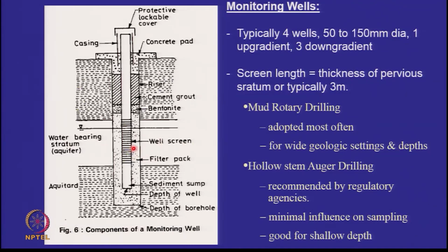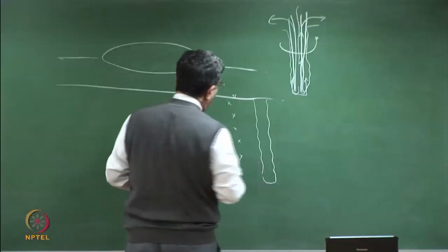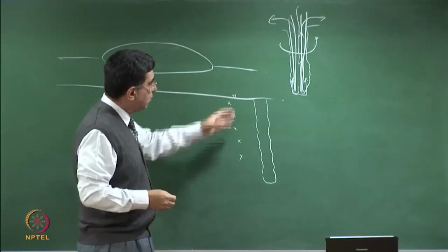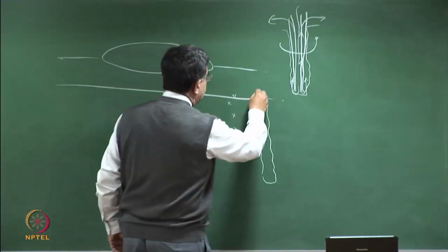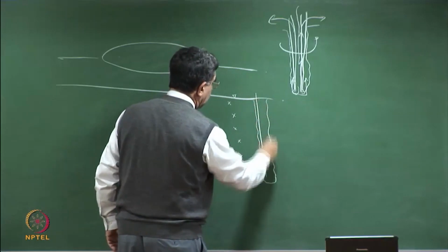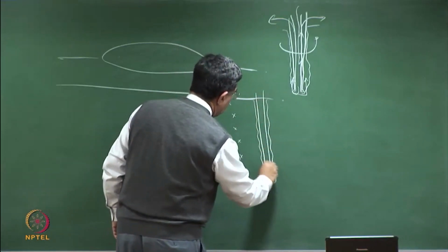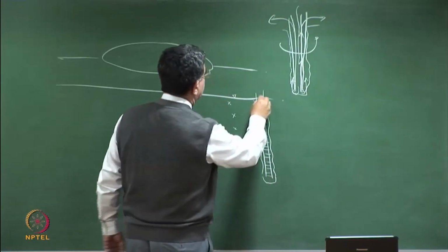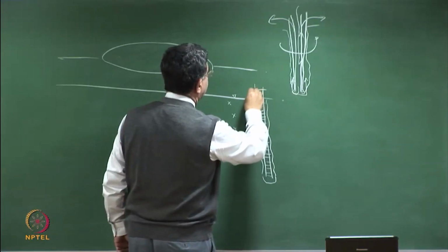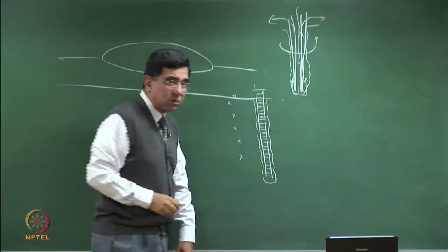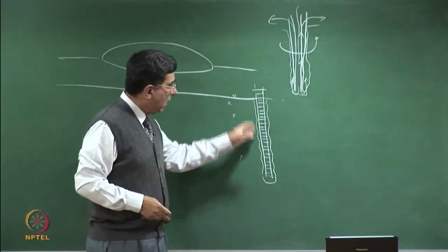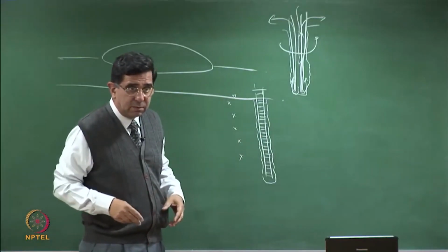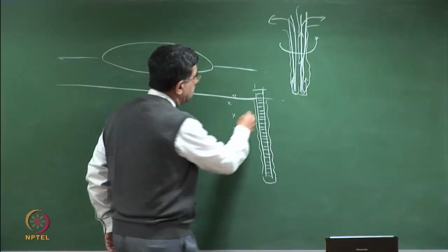So when I give you this problem, that please tell me the chloride concentrations in the groundwater at these 5 levels, you are very tempted to put a borehole. Suppose you put the screen, you say, I will put the screen over this entire length and then I will take the samples from this borehole. Please understand the gravel outside is making all these waters mix together. You know, this has become a high drainage media.